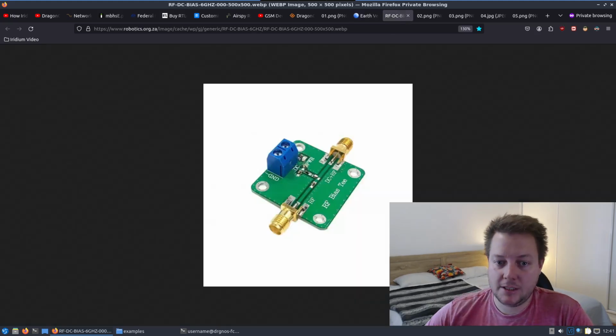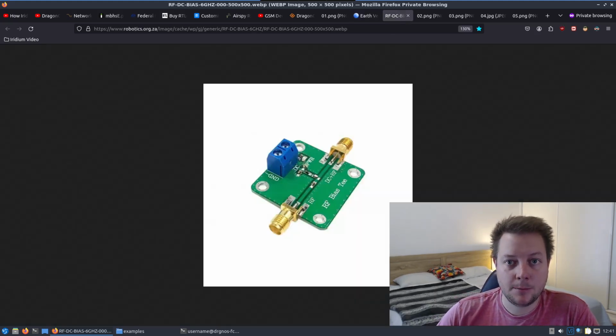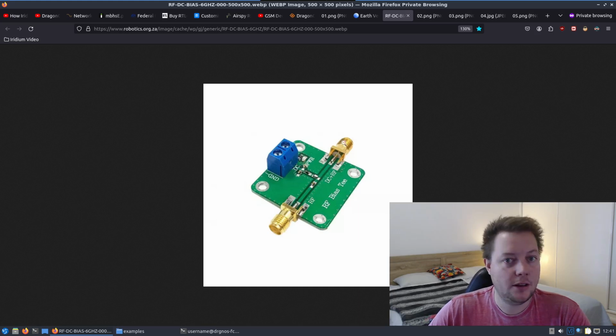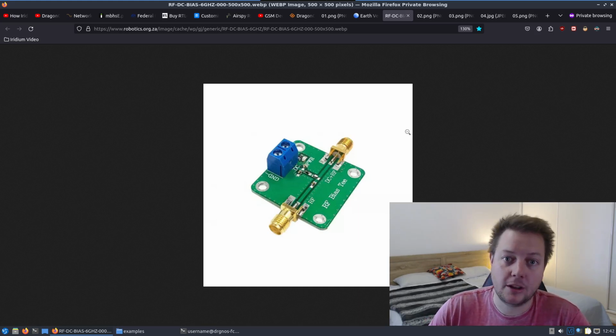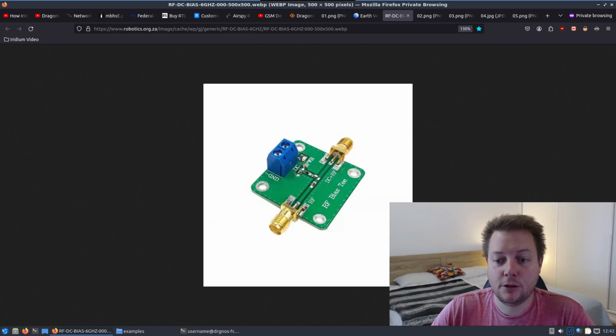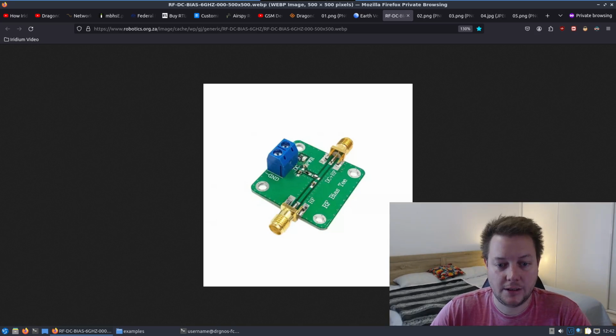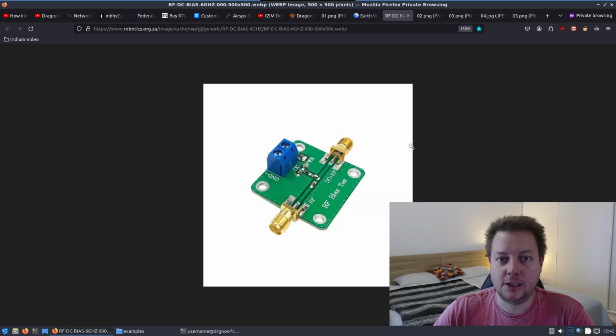A bias T is the circuit inside some software-defined radios, but not all, that provides electricity through its RF port, and then through the coaxial cable, for the purposes of powering a low noise amplifier, active antenna, or other inline devices that need electricity. The voltage supplied is about 4.5 volts at a relatively low current, something like 250 milliamps, around there.